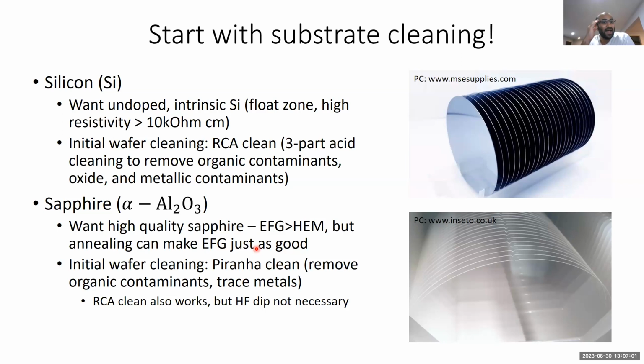if you don't want to do an acid-based clean, you can also just do a solvent-based clean, just using regular organic solvents like NMP, acetone, isopropanol. It really seems that if you want to get the cleanest wafer possible, you should do these more aggressive acid-based cleans.